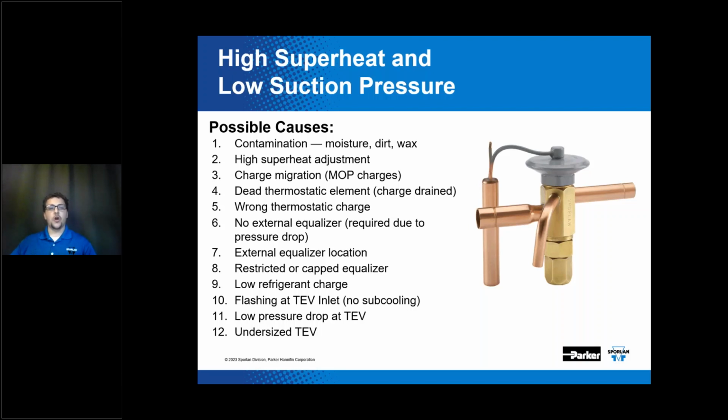You could have no external equalizer, meaning you have an internally equalized valve in an application that should require an externally equalized one. You could also have a capped equalizer, which we've seen, right? If it has that third connection for the external equalizer, it has to be connected. We've seen instances where the contractor or the technician has capped that off, and that's absolutely problematic.